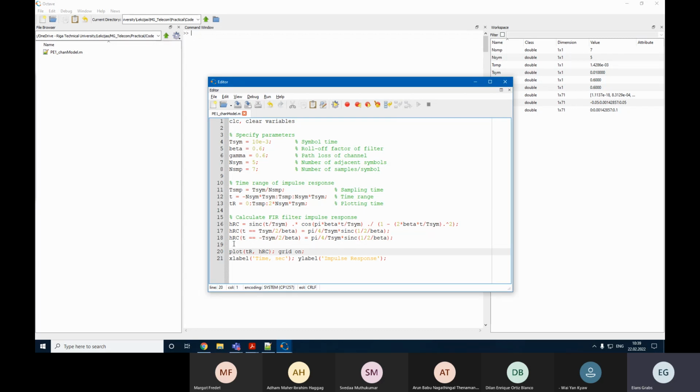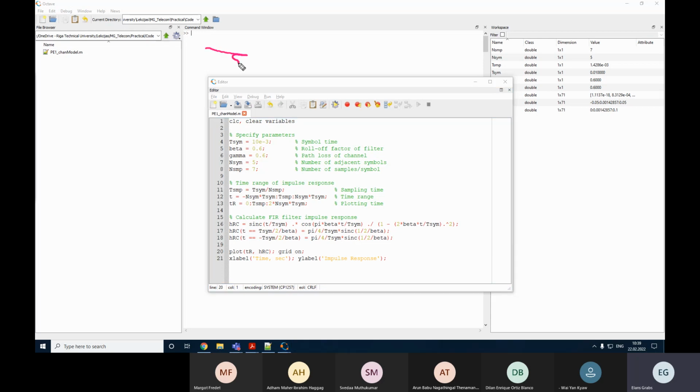To do that, we need to use the Z transform. Z transform replaces in our filter expression. Basically we have our filter expression specified like h0 plus h1 z minus 1 plus h2 z minus 2 and so forth for as many symbols as we have, and we have 71 of them in total, right?